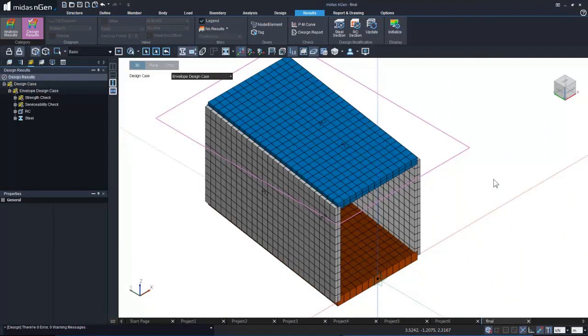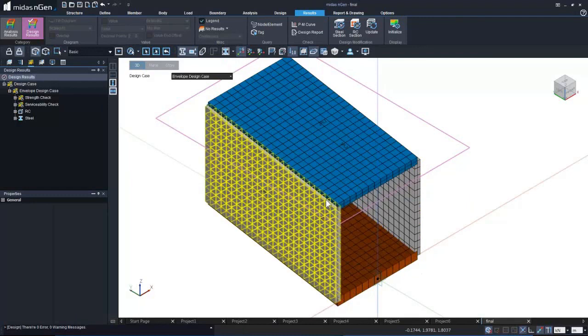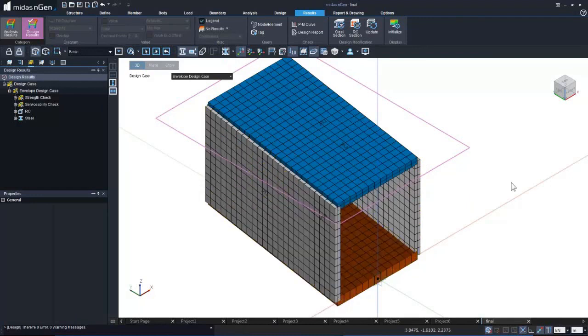In addition to our simple box, you can also have wing walls added to it by simply sketching and creating faces or plates. It's like creating a model using AutoCAD. So it's very simple. Just visualize what you need to do and create 2D elements, 2D members at any location that you wish. And the program basically will take care of the connectivity of the members. Alright, so that is it regarding the box culvert. Let me get back to the presentation.